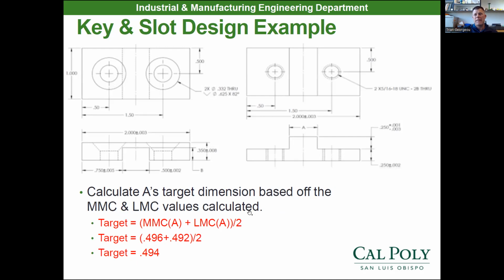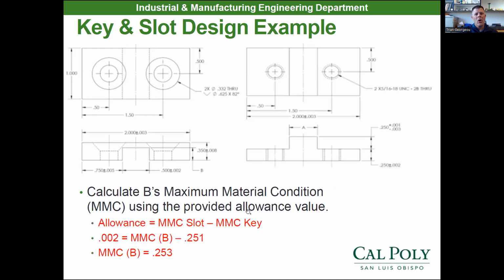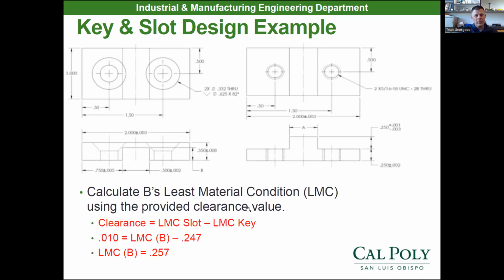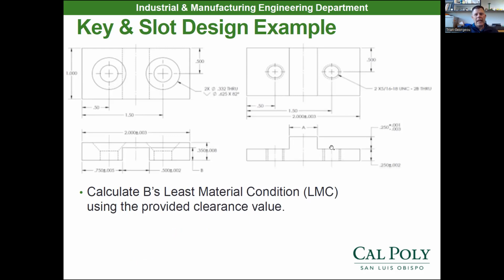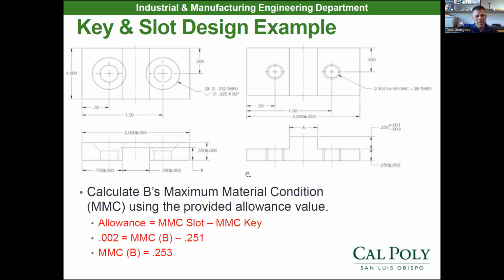And all my parts would have between 2 thou and 10 thou of clearance when I went to put these parts together. That's how you design parts that fit together. So hopefully you understand how that works now. So let's try it one more time.